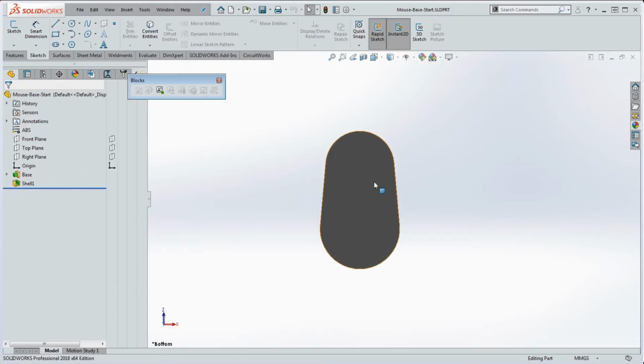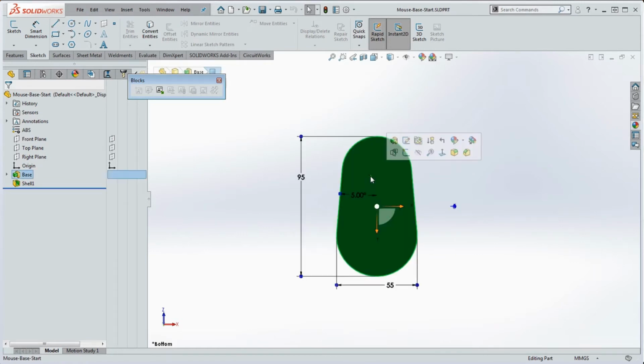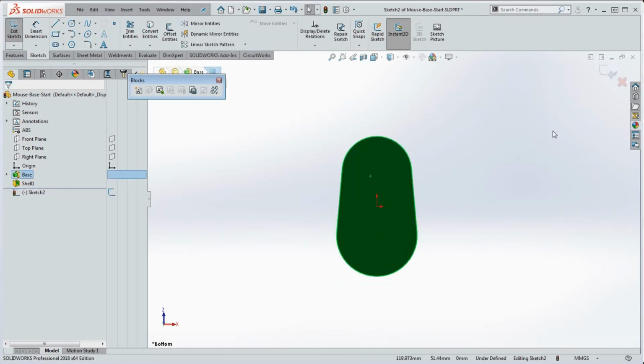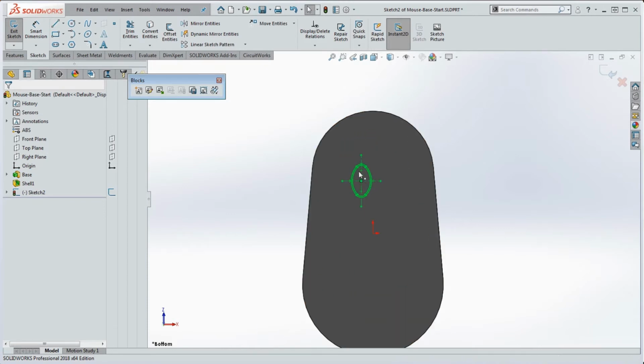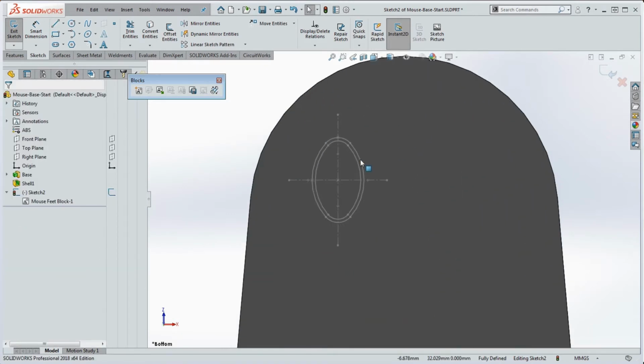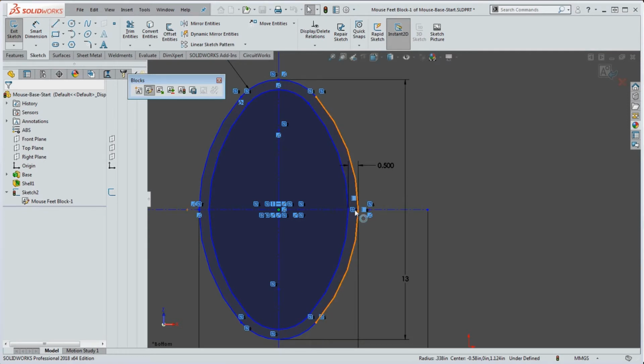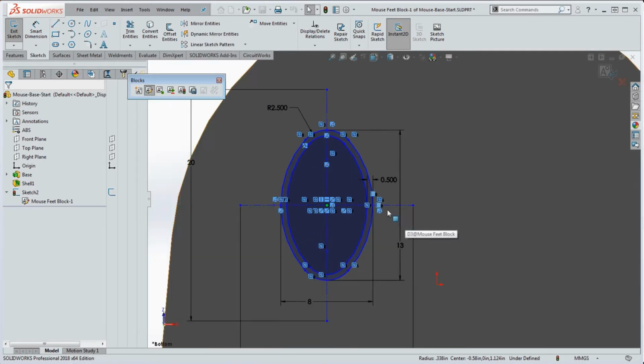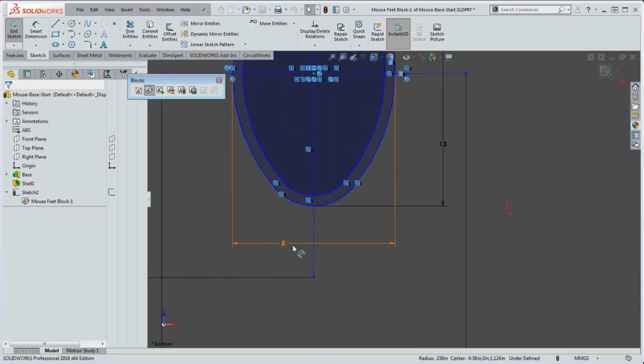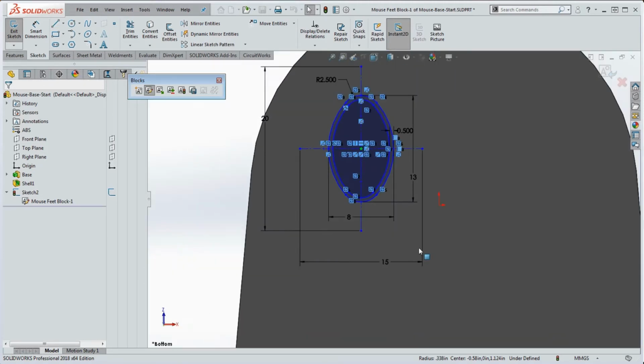Now we're going to go back to our other part. We're going to insert that. So we're going to click on the surface, go to Sketch, and just do Control V, and there's our block. So the block is going to be continuous here, and again, if we double click on it just to make sure, we have our dimensions in here, 2.5 millimeter dimension offset in here. We have our offset sketch entity, and these other dimensions in here, which actually define the outside elliptical shape in a way, which is 13.8, and then that top arc at 2.5. So everything looks complete.